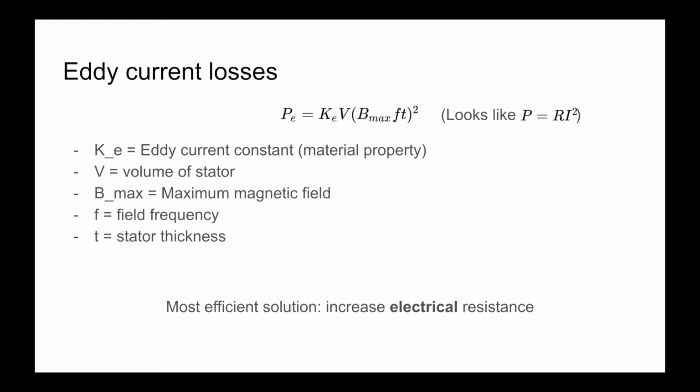When doing so, we have two options. We can either decrease the resistance R or decrease the current I. However, from Ohm's law, we know that if we decrease one, the other will increase to compensate and maintain the same voltage. So the question is, which do we do? It turns out that it's more efficient to increase the resistance and decrease the current due to the quadratic dependence on the current. One can analyze the situation in which the resistance is doubled, cutting the current in half. While the voltage of the system stays the same, the power dissipated is overall cut in half.